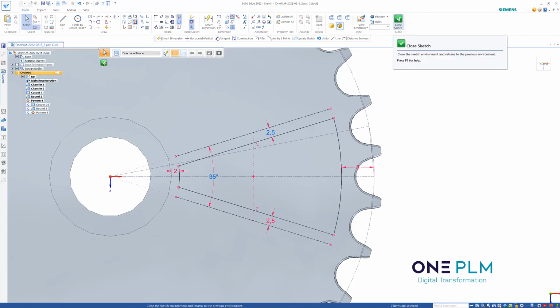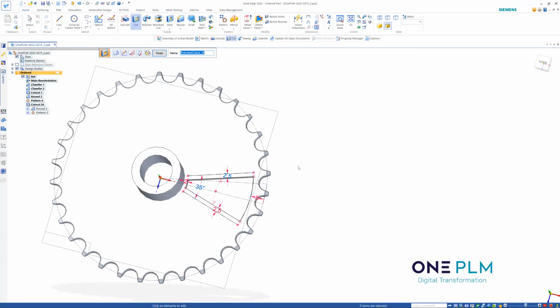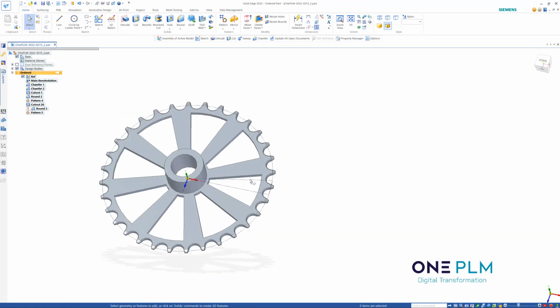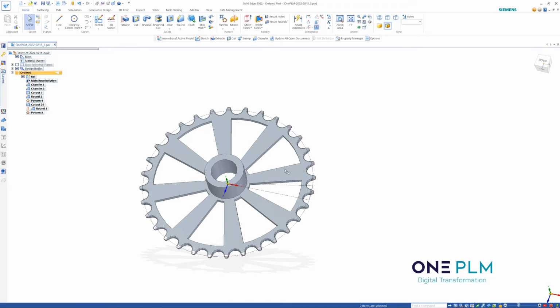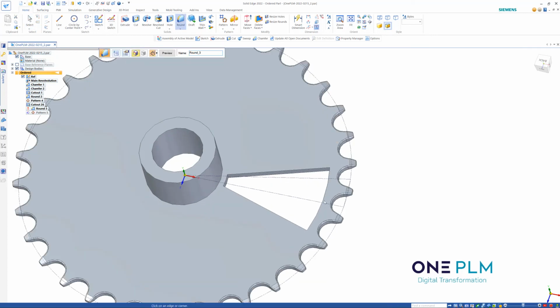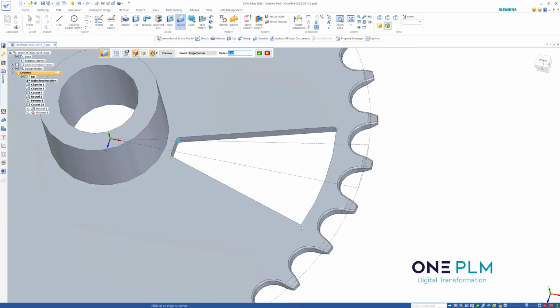Okay, so now we can close the sketch. That -10 we added earlier, we can probably go and delete that. And we also need to go and correct our round as well. So that -10 is still doing something strange. So first I'm going to go and correct the round, go back to our edges. It's picked up that we've no longer got those edges, so let's go and redefine those edges. If you do click the wrong one, Control and click deselects that edge.